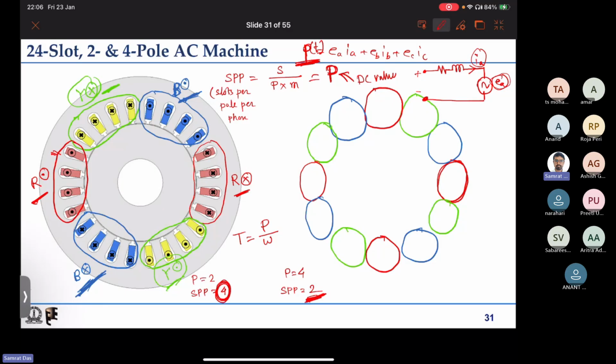So the variation in speed is very low, because we do not have any harmonics in power, or we have a constant instantaneous DC power input, or power converted to magnetic energy. That means this equation tells us that we have no torque pulsations also. So basically in electrical machines we can have zero torque pulsation.